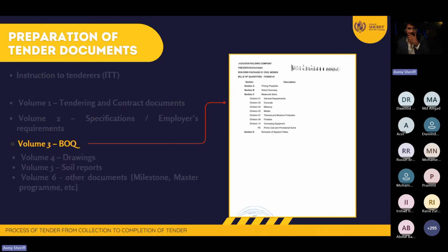Who is best? One person says demolition as an entire item is 1 million. Another says demolition is 5,000 riyal per cubic meter. Another says a linear item, so and so. How can you compare? You may think that 5,000 per cubic meter will be cheap, but when you go and measure, that may go up to 10 million maybe, right? So how are you going to compare that? What you need to do is prepare a standard document.